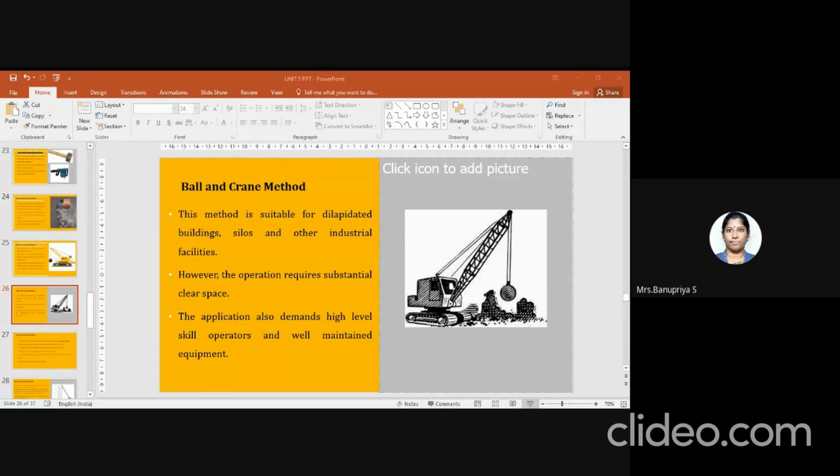Okay, so in order to avoid those things what you have to do is, while doing the demolition or before the demolition, spray water all over the building. If you spray water during the demolition or before the demolition, you can avoid much formation of the dust. You can't avoid it fully, but you can avoid it to some extent.